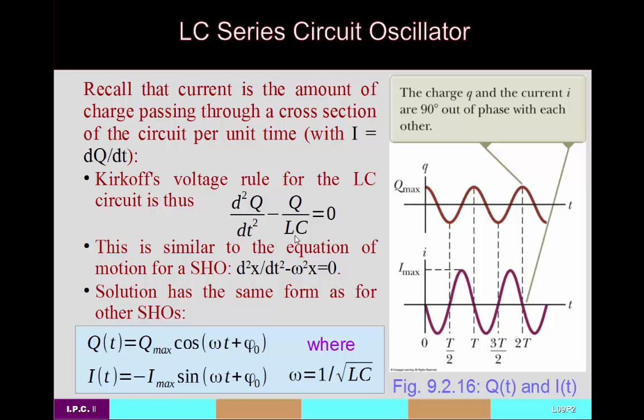So this is obtained by way of the fact that current is the derivative of charge with respect to time, and we started with a derivative of current with respect to time, so that must be a derivative d by dt of this, so that's d squared Q by dt squared. And we've basically collected all of the non-Q terms with our Q, not with our derivative term.